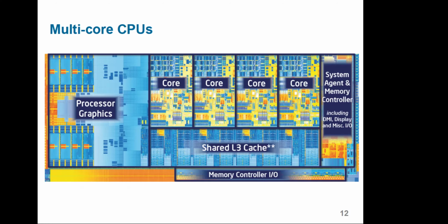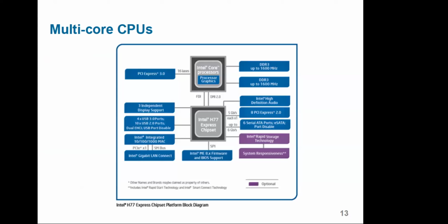The memory controller is what connects, literally with wires, to the RAM, to the memory. This is a part which basically operates the hub, the bus. The bus would be the wires themselves, but this takes care of the communication between the memory and scheduling of the cores, distribution of workload along the cores. So the data comes through the memory to the cache, and then the cores read it from the cache, do something with it, put it back to the cache, and the memory controller puts that back into the shared computer memory.